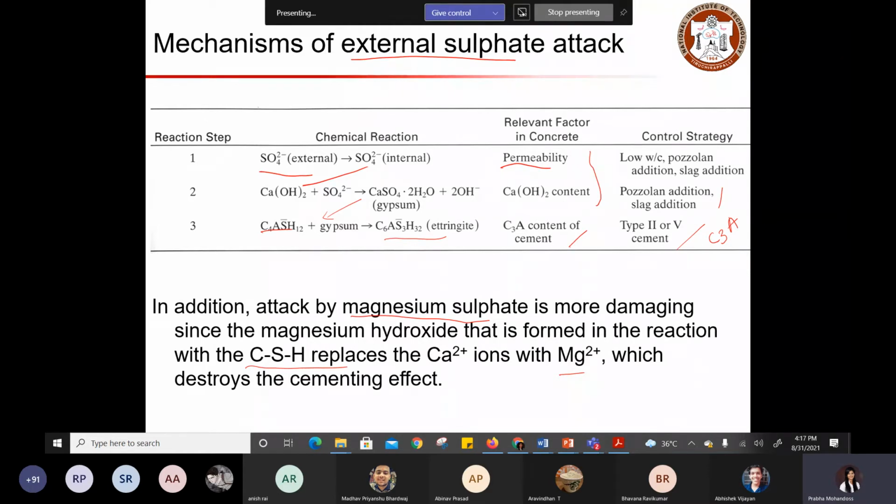If you have a huge quantity of pores and calcium hydroxide, that leads to other deterioration mechanisms by letting elements enter your concrete and then reacting with them, mainly the calcium hydroxide, which could react with the elements entering your concrete. In this case, you have sulfates.